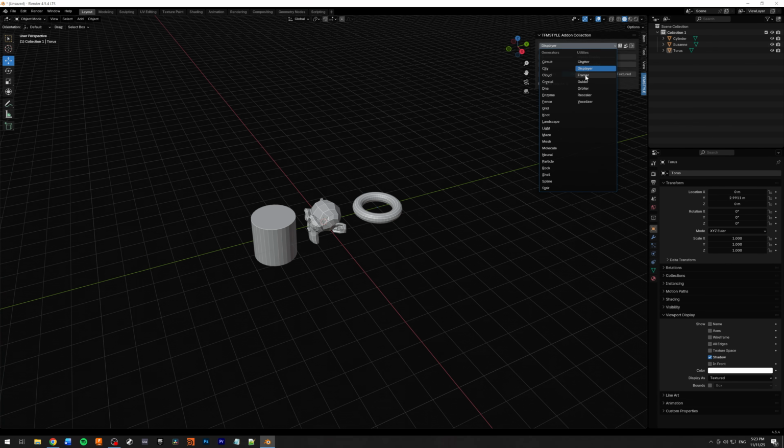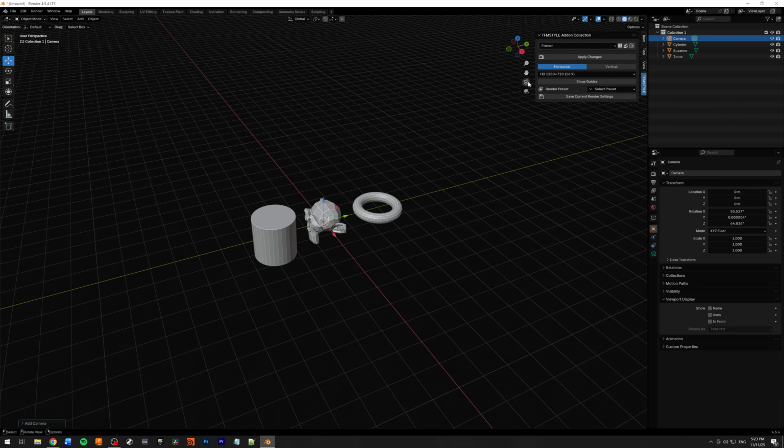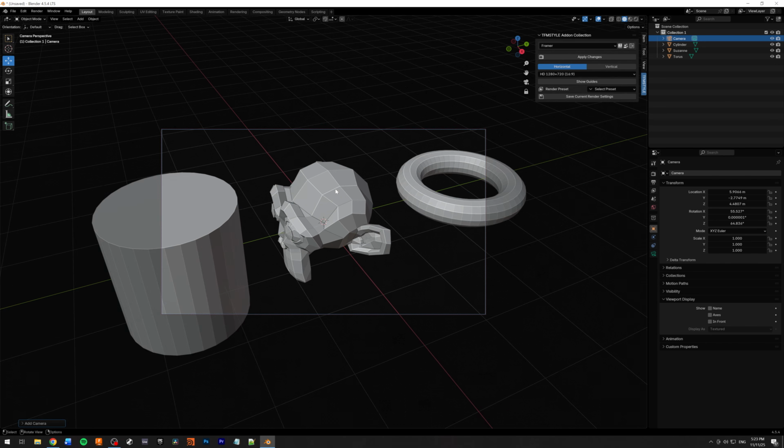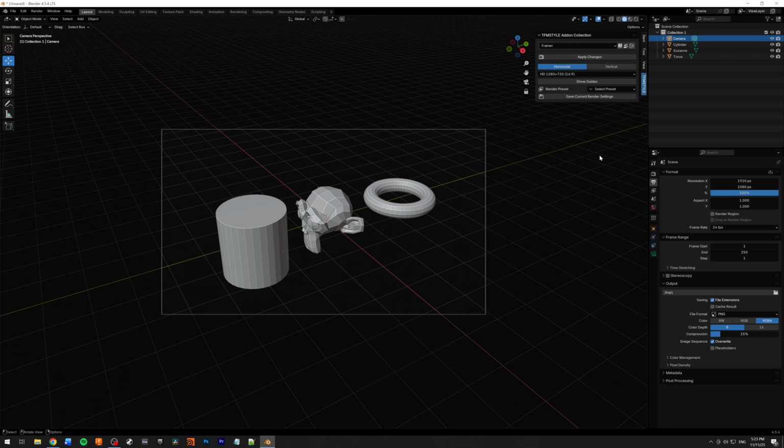All right, let's go to the Framer add-on. So the Framer add-on is a camera utility. So I'm going to create a new camera. I'm going to jump in, go back just a little bit. I'm going to turn here my output settings so you can see the change. So the Framer add-on is kind of a library preset of different aspect ratios that you can select through. So in this case, if you want a CinemaScope aspect ratio and resolution, you can select it, click apply, and as you can see now, the resolution will change automatically.